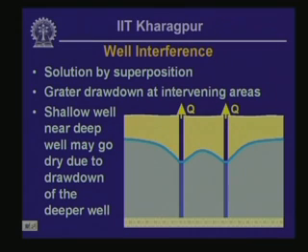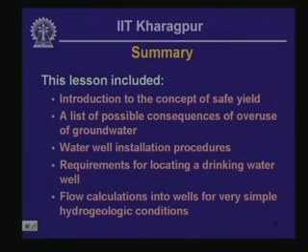You should also note that with this kind of well interference, if you have a smaller well working originally at a location where a larger well was installed at a later date, because of the drawdown of the larger well, the smaller well in fact can go dry, and that type of problem is encountered in many different locations of our country.